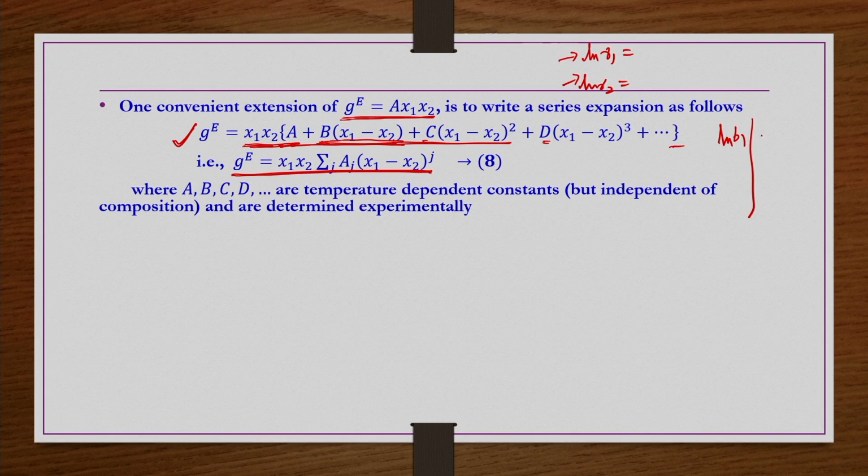Then you can find out the activity coefficient for that solution experimentally, and then curve fit that data using this expression, gamma 1 infinity is equal to exponential of A by RT, and then you can find out what is A for different temperatures. That is simply by curve fitting, or let us say under any condition, if you plot ln gamma 1 versus composition x, you may be having different curves like this. So, different curves for different temperatures, and then you can do the curve fitting and get those parameters A, B, C, D etc. through the experimental condition.